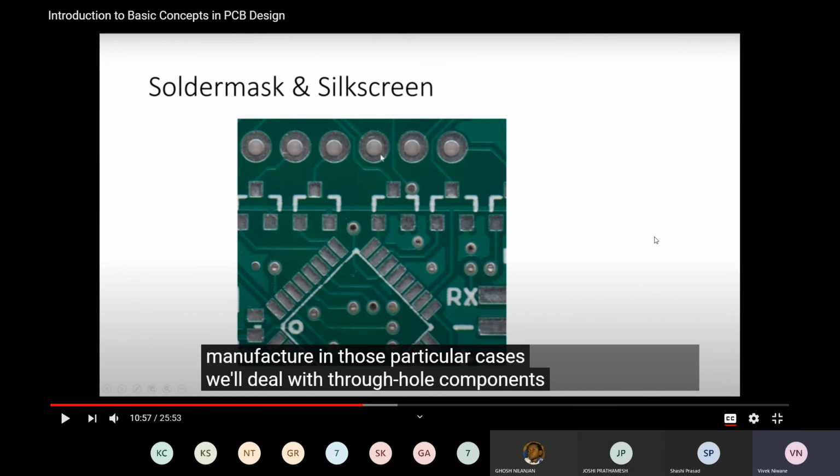So it is important to have vias and traces which are running throughout your PCB. Vias connect those traces. Vias may be in between the layers or in between the top and the bottom layer. Okay, so we have to take care of the vias because those will act like a waveguide. If we are working at megahertz frequency for that particular via, then that via, due to its cylindrical nature, will act as a waveguide for megahertz frequencies. Okay, so we have to take care of lots of issues over here.